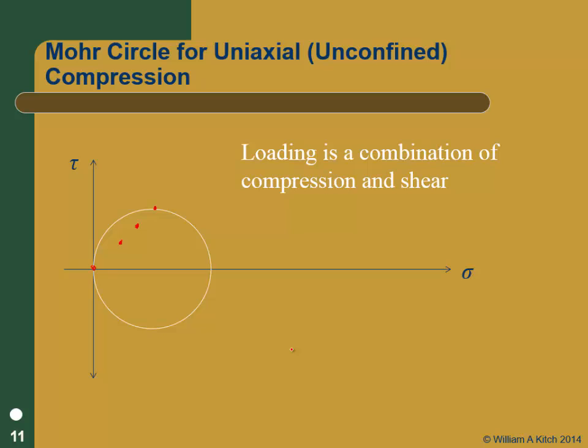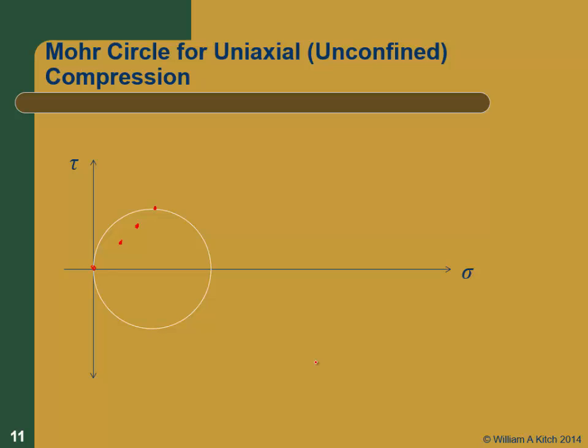Notice that, let me just ask the question: is there any shear in this? Is this a sample at this point where I've loaded it on the top but not on the sides? Is there any shear in that sample? Did I apply any shear loads to it? I just applied normal loads to it. But you tell me that sample is in a state where it has shear? Sure. What's the maximum shear stress it has? It's right here, right? That's it right there.